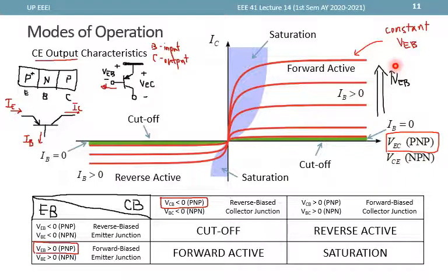Now this plot also shows us the current source like behavior of the BJT under the forward active case, since even as we change the reverse bias at this portion, the current does not actually change that much, because as long as the holes are able to get into the depletion region, then they would just drift into the collector.